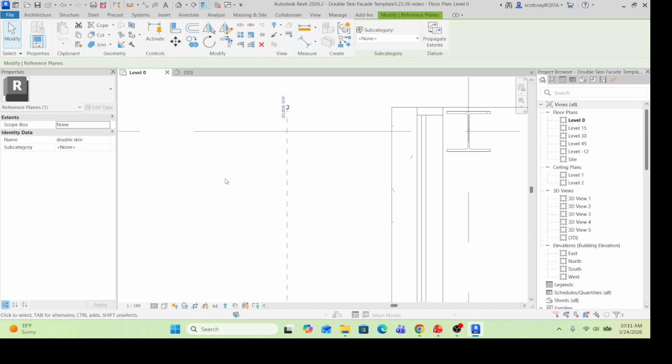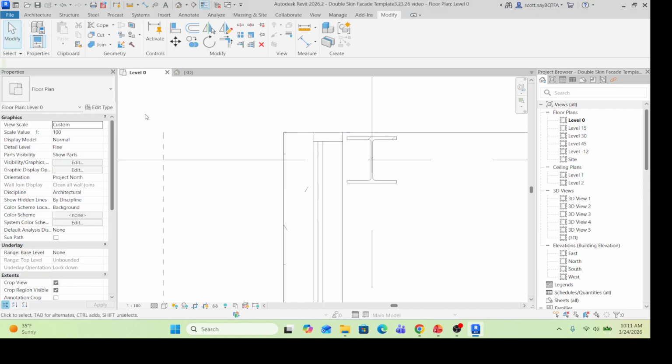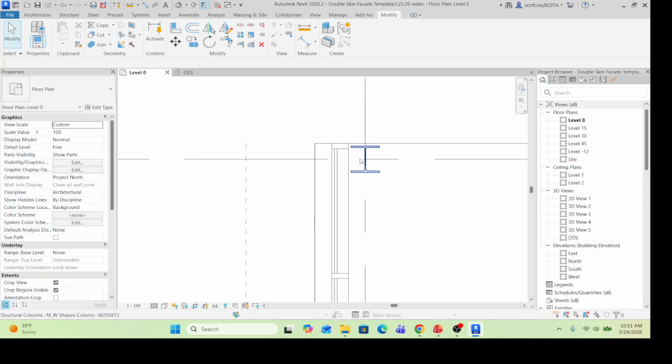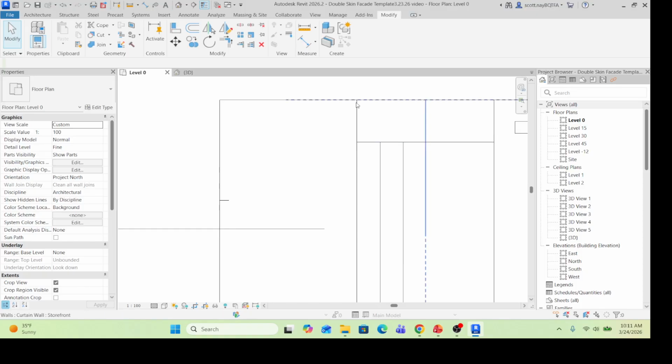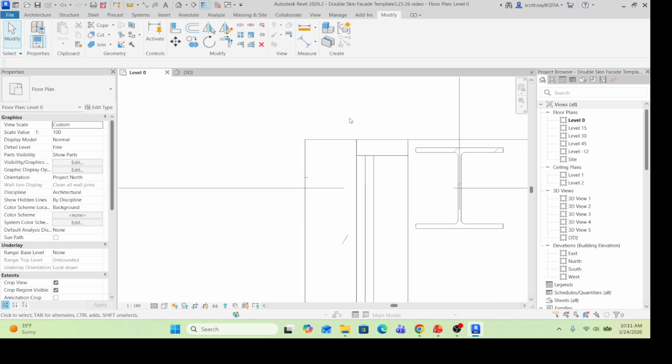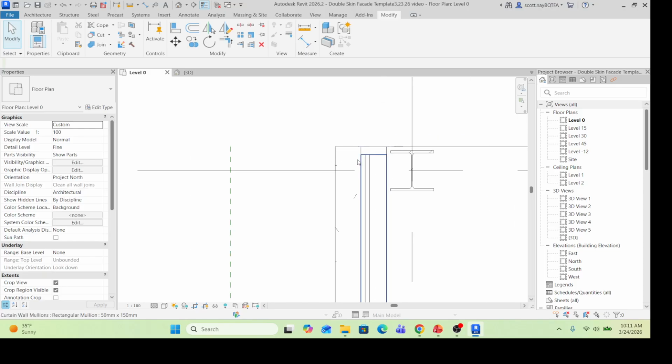I don't want it to be buried underneath. Well, I'm not really going to need it after that. But because I designed my custom one with the mullions going outside of all the reference planes, if I draw it to the edge here, it's going to come 2 inches past. So I need it to end at the inside of this when I draw my mass, and then that'll make up for it.